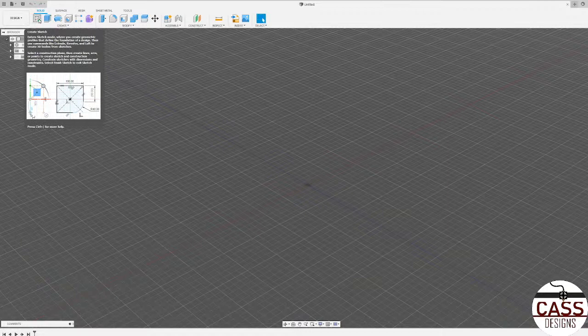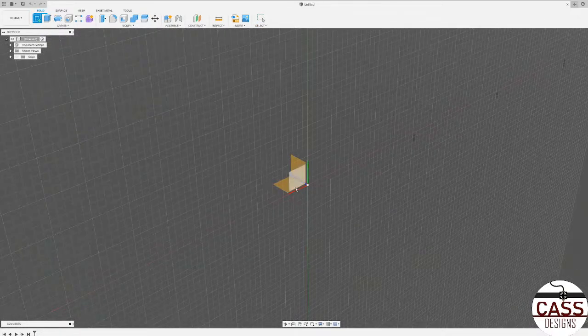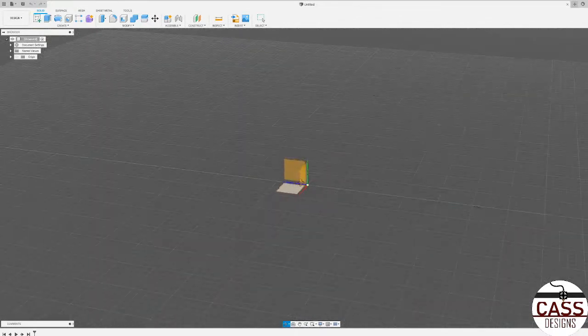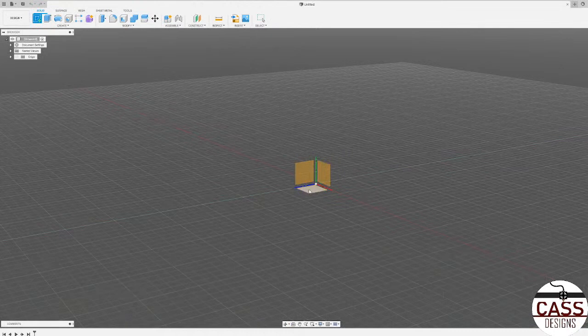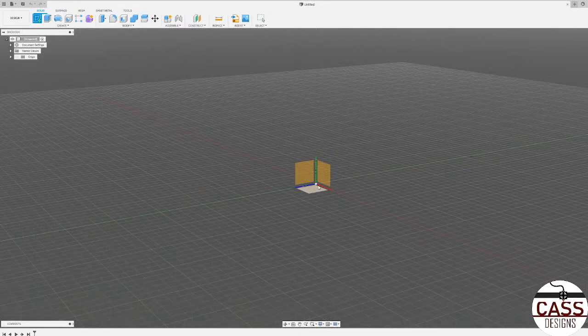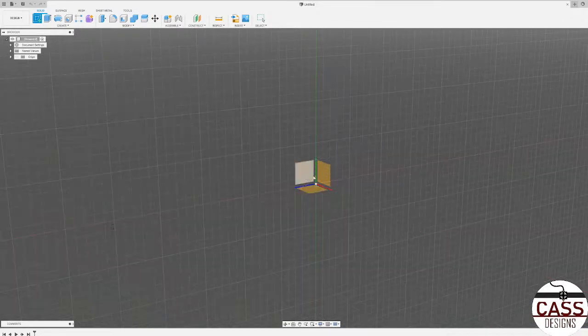for 3D design, the first thing you usually start out with are sketches. A sketch is a 2-dimensional drawing put onto a plane. You can see right here these 3 yellowish orange squares. These are your planes that you can start the sketch on. Basically you have the origin right here, that big circle, the origin of this 3-dimensional grid that you use as your play space.